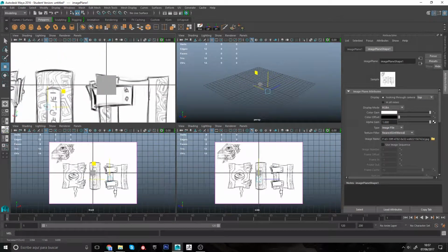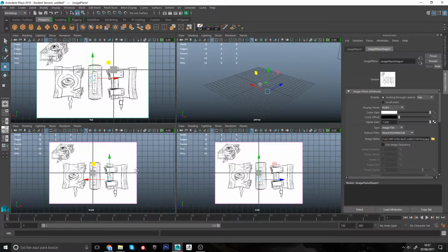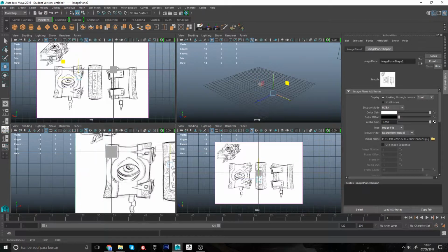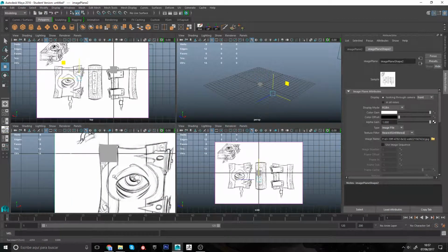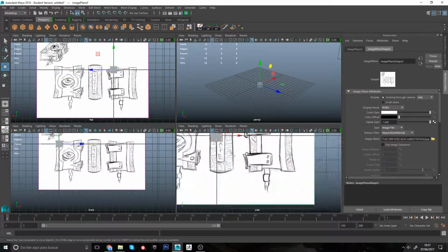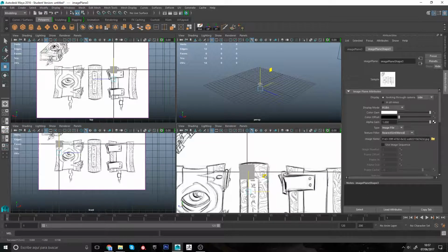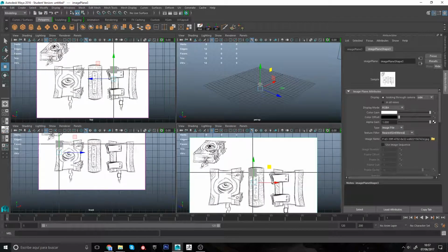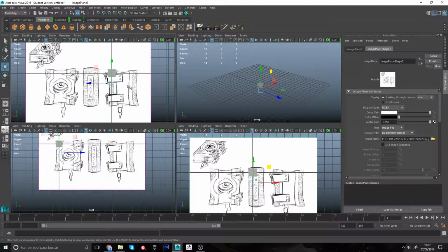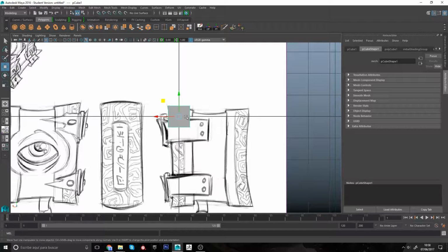We need to move our object through the viewport to fit our cube in the same point in all 3 views. We need to have one of the views as the main view and the rest should use this as a base. If you place the mouse over one of the 4 views and press the spacebar, this view will expand and we can work more comfortably on it. If we want to go back to the 4 views to change to a different one, or to work on all 4 at the same time, then just press the spacebar again.